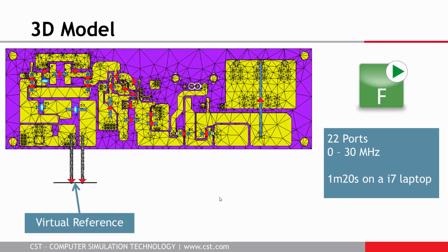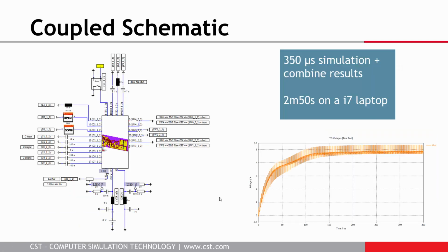And then, in the same way that I have connected all the elements during this webinar, I connect all my switching elements, the diodes, the capacitors, the line impedance networks. I connect them all to this block and run the full coupled simulation. It takes some time till I reach steady state, but for 350 microseconds of simulation time, till the steady state of 5 volt is reached, it takes approximately 3 minutes on my laptop.